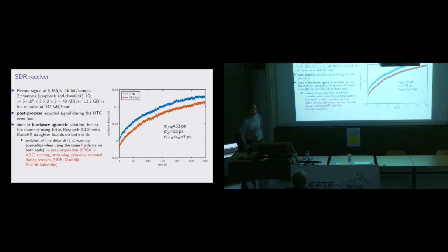Until we looked at the loopback signal. What we're doing in our system is the X310 sleeps, wakes up at the second before the broadcast, starts emitting the signal, and then we start recording, meaning the FPGA and the ADC are cool. And then for 5 minutes, they just keep on accumulating the data, warming up, and then they sleep again.